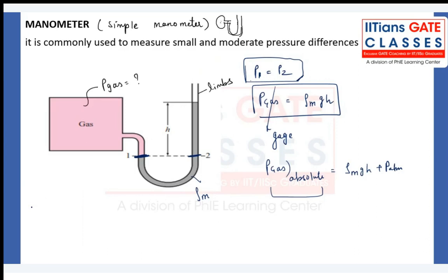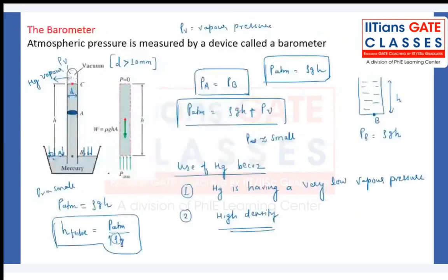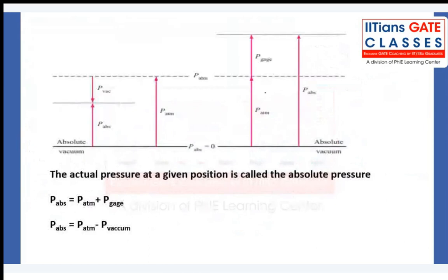No, Ravi Teja, try understanding. If I want to measure the gauge pressure, directly the rho g h value will give me the value. But if I want to measure total pressure, because I told you, if you see the diagram, it is very clear from the diagram itself. There should not be any confusion. See here, gauge pressure, we know that rho g h. But if I want to measure total absolute pressure, I need to add P atm. There should not be any confusion, right?